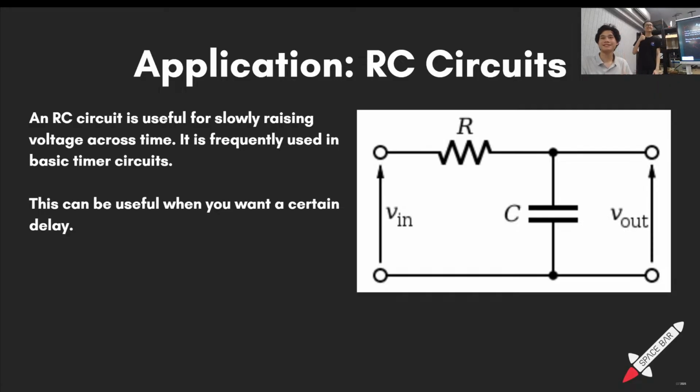Okay. This is to delay your voltage build-up, not to delay the current flow. Yes. There is another graph for current which looks like this. Actually at the beginning the current is high because the capacitor isn't blocking it, but when it's full, the capacitor blocks it, and the current drops to 0. Because they are cancelling each other. Yes, close enough. The current flowing through the resistor is the same as the current flowing through the capacitor.